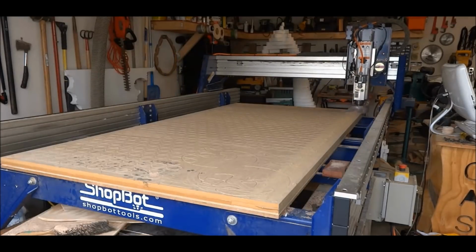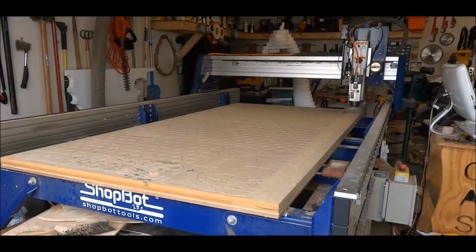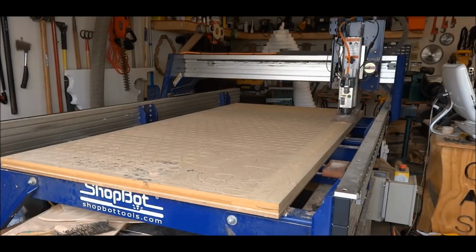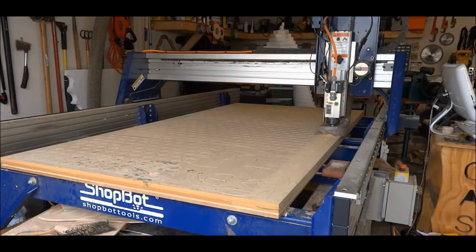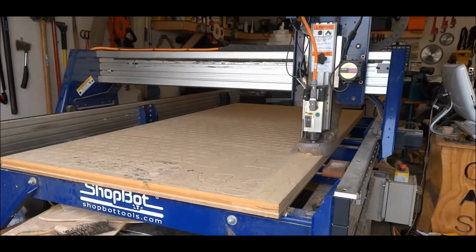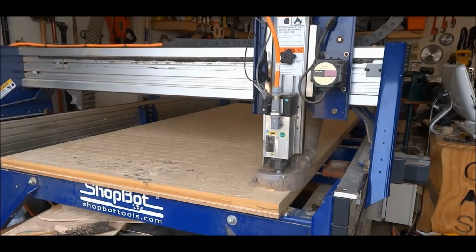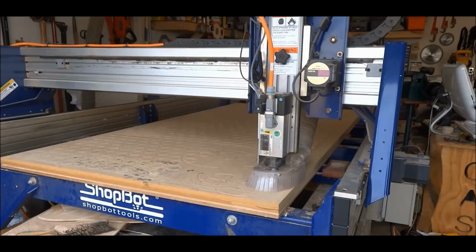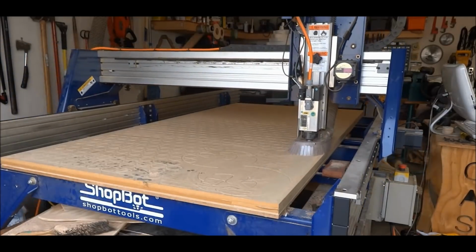Alright, you can see all three of these tables that we've looked at have been used. You can see obviously the cuts in the spoil board, but what you can't always see are any warps in the board that you've had maybe through different moisture levels and whatnot in the air. So I would always recommend working on a flat surface table, and that will really help with your cutting.